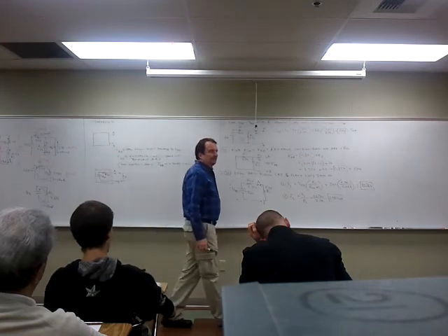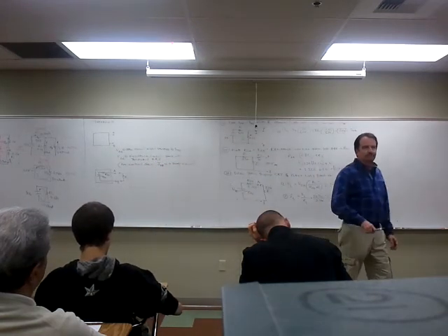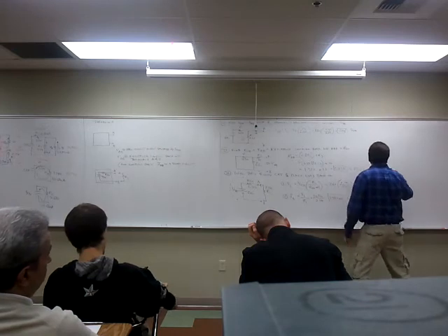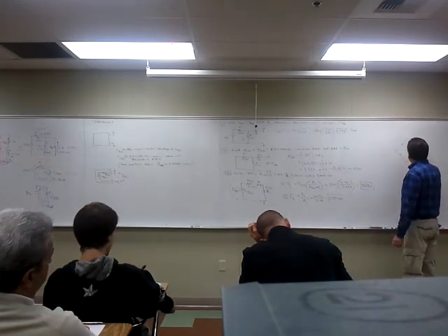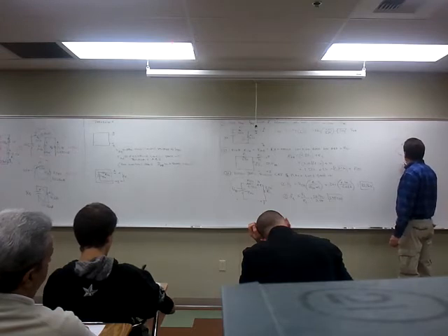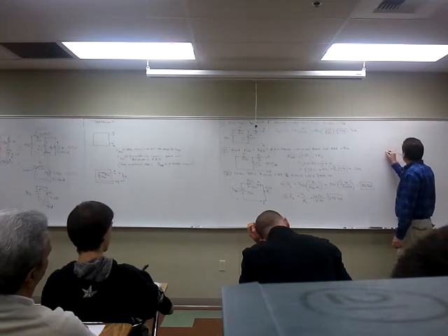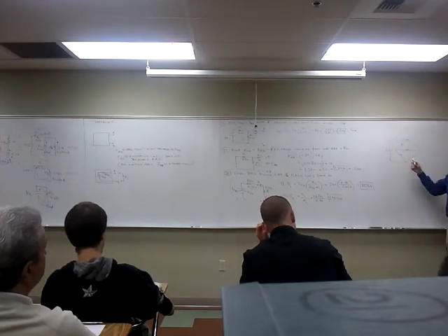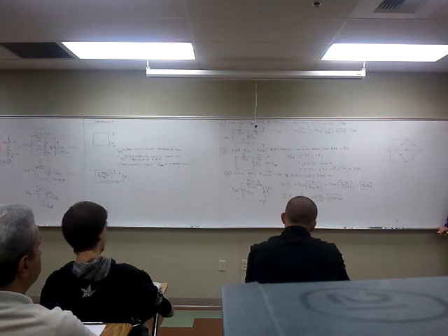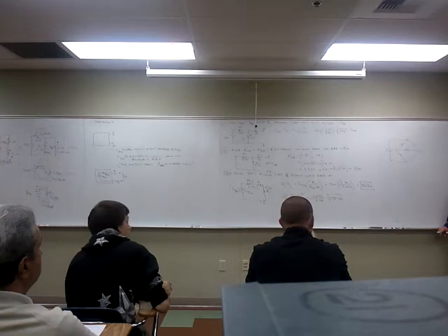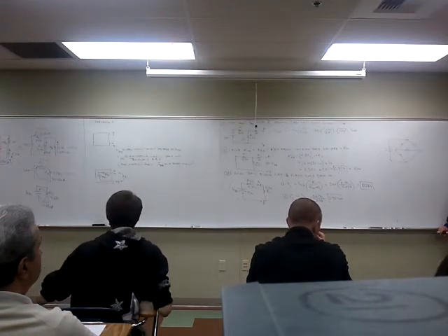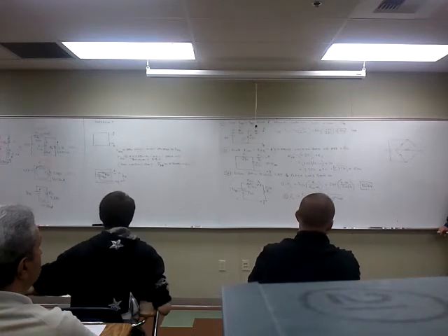Now, which resistor did I call load here? I just picked one that I called the load. We're going to do this later, but just let me make a point. Don't draw this or anything right now, because I'm going to do this later. This was the Wheatstone bridge. The Wheatstone bridge has this form. Is any resistor in series with or in parallel with any other resistor? No. Can you use normal series parallel techniques then to solve that circuit? No, it's impossible. That is an impossible circuit to do, where you have to combine 2 elements at a time.